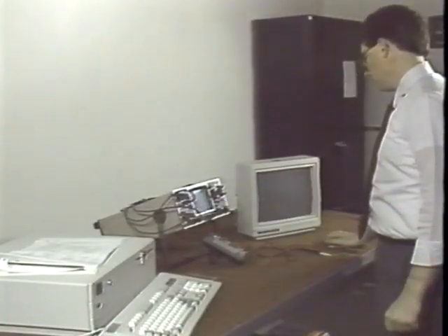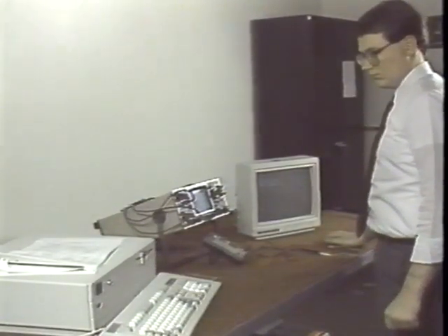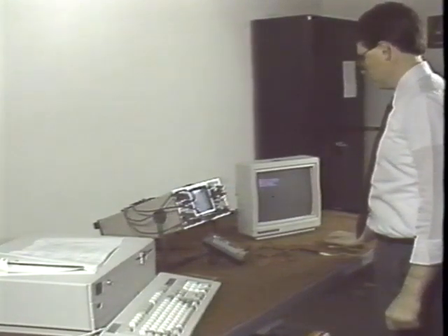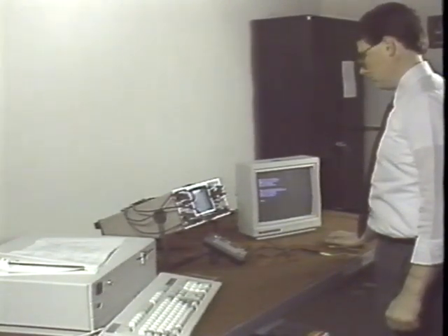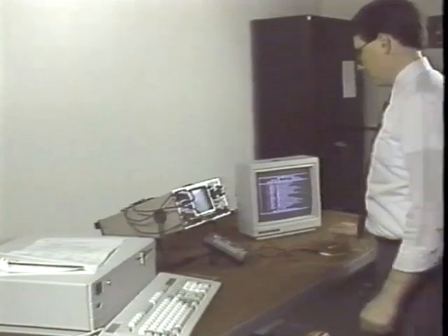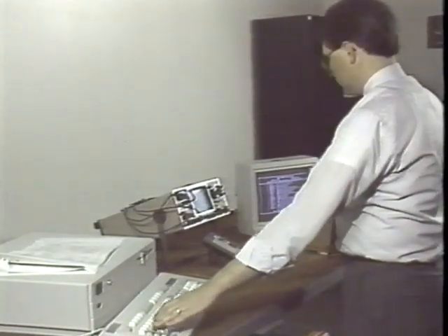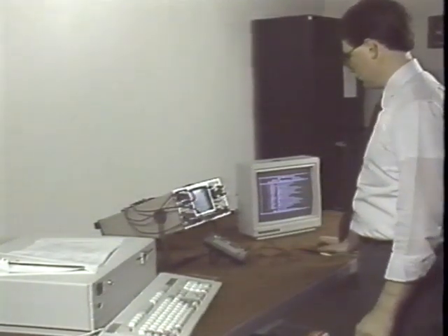Color monitors contain most of the same controls that monochrome units do, such as power supply, sweep, and focus adjustments. Do these before beginning the color alignments. It is also a good idea to degauss the unit before beginning the color alignments. This will reduce the effect of residual magnetism on the alignment.